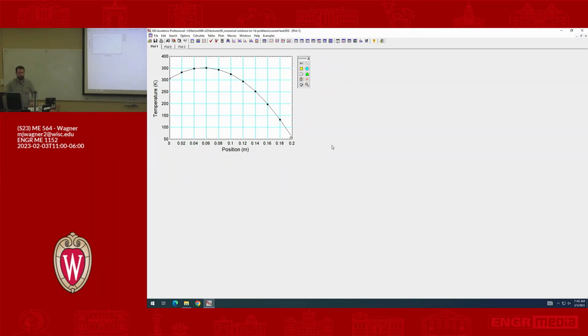OK, yeah? The 40 Kelvin temperature that we had earlier in the problem statement, is that at the node, or is that in the volume? It's in the device that this wire is attached to. But there's a contact resistance between node N and the device. Right? So there's going to be a temperature drop there. So node N is at the wire, not in the volume.